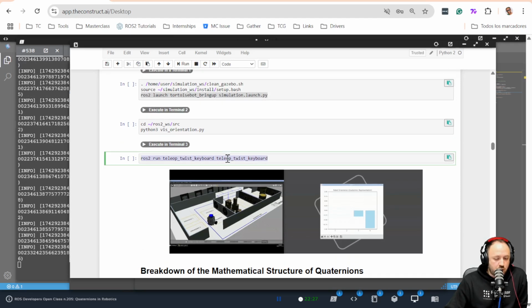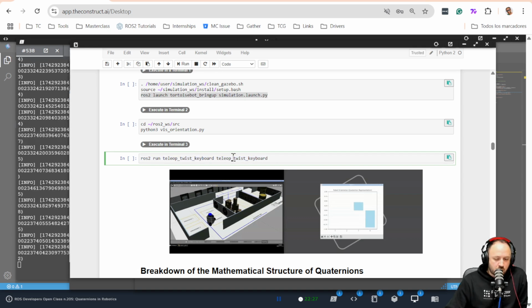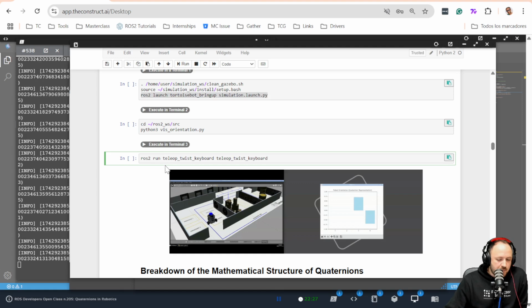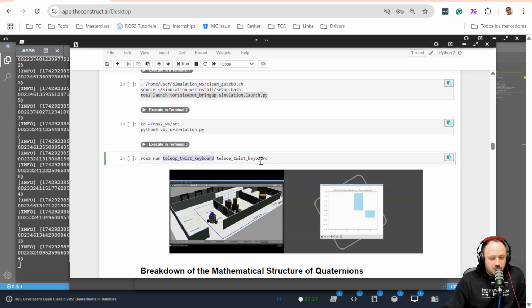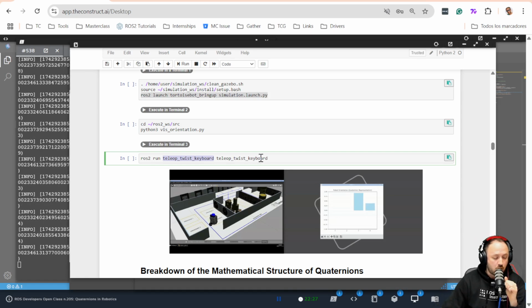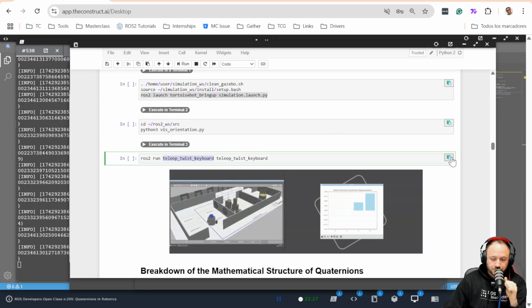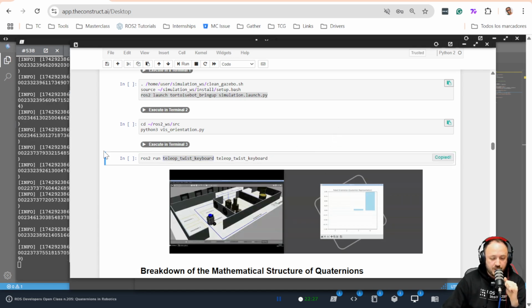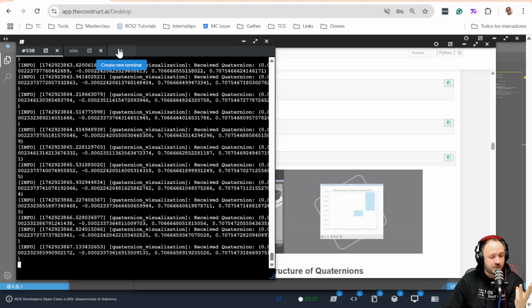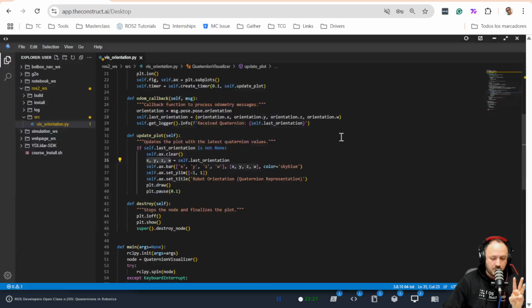Then for this, we can use a very well-known program in ROS and ROS2, which is the teleop twist keyboard. This program, as probably most of you know, allows you to move the robot, to send velocities to the robot using the keyboard. So I'm going to copy this program and I'm going to open a 3rd terminal. I need 3 terminals. First one is running my Python program.